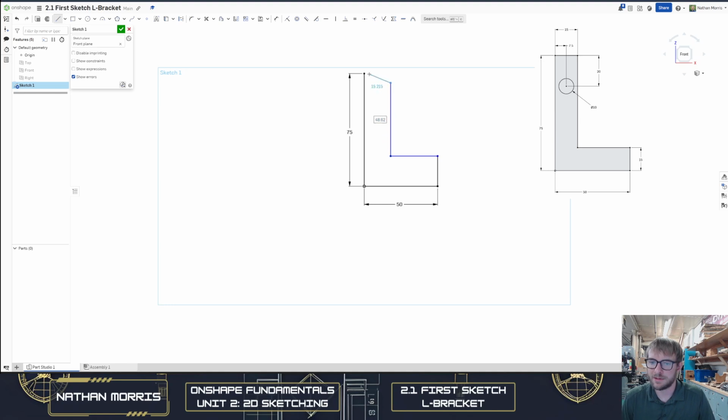I'm going to do this vertically, and I'm going to create this line purposely slanted. But then I can select this horizontal constraint up here. So it's the flat line, and I can click on that line and it'll lock it in horizontally. Pretty cool. I still have these two blue lines because I haven't added some constraints that I need, namely dimensions. So I'm going to add dimensions.